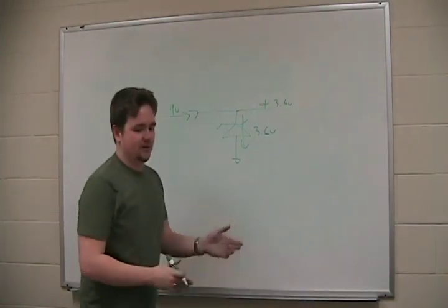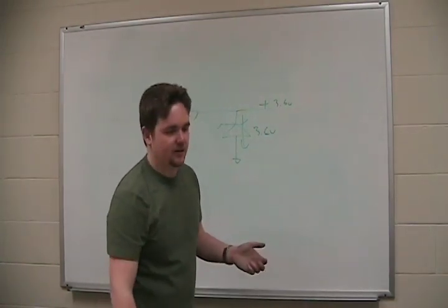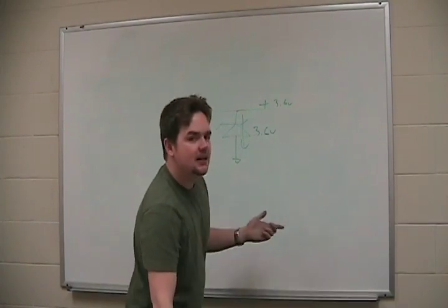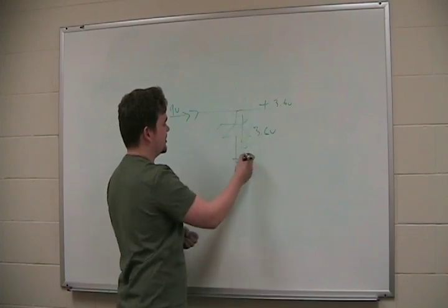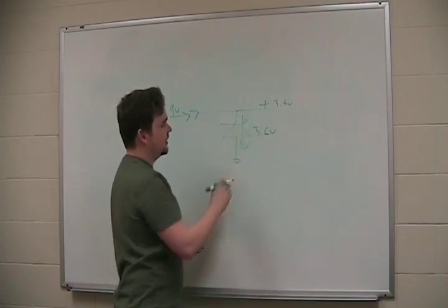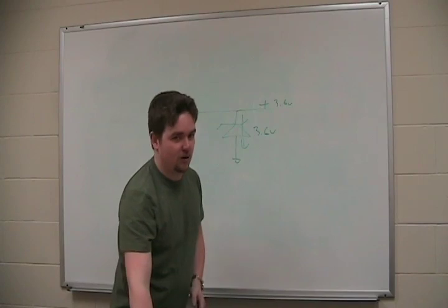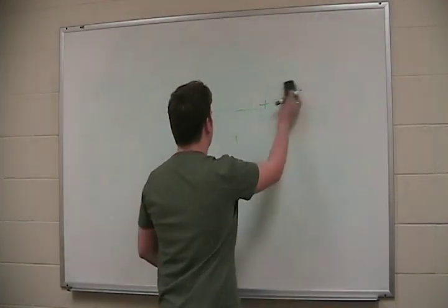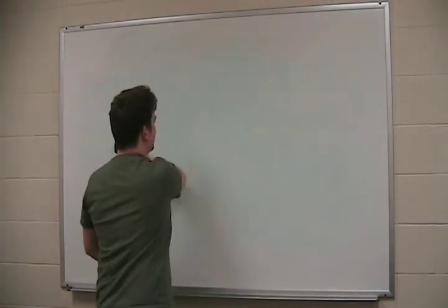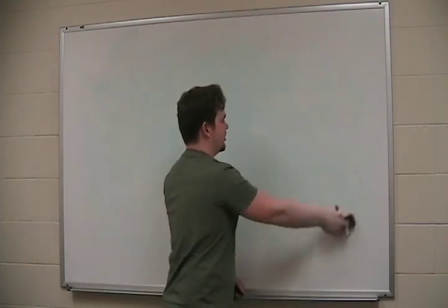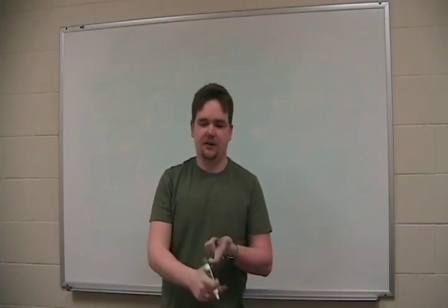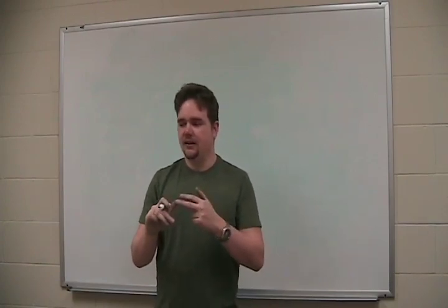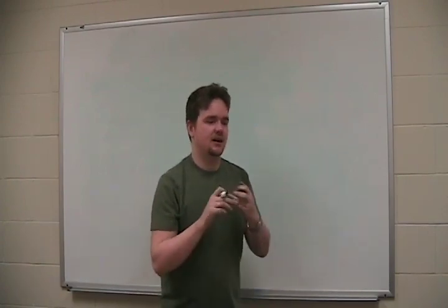But don't ever substitute this for a 7805, because if you have too much current across this, you don't limit the current across here, you're going to fry your Zener diode. They're very small, they're very fragile. They're nifty though. But diodes are used in receiver circuits, they're in rectifier circuits, they're in limiter circuits, they're in tons of stuff. They're in feedback circuits, they're protector circuits.